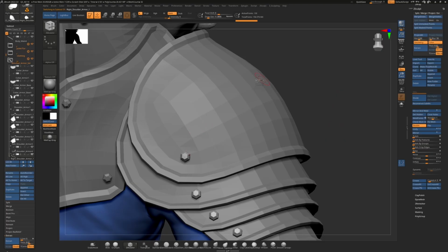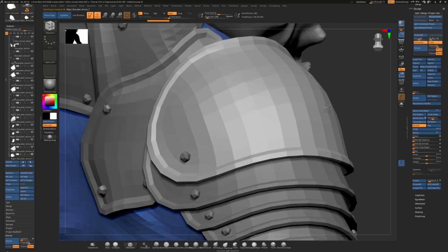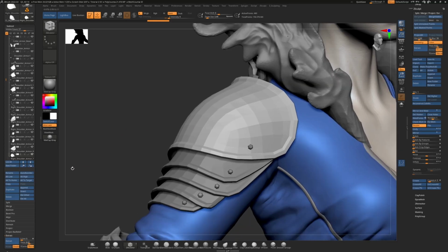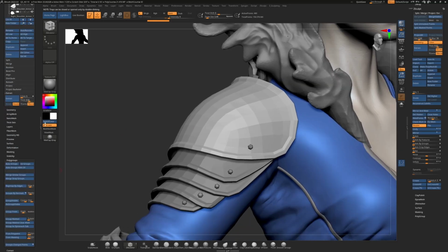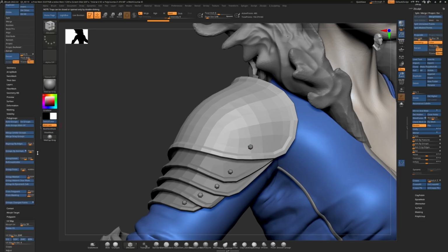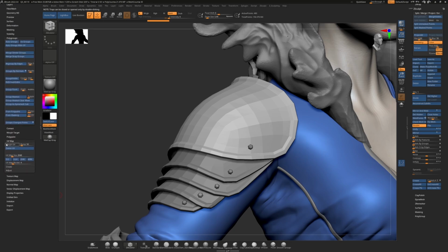The only way you can do that, again, is if you have UVs on the model that you're actually placing the IMM or curve brush on. This model specifically, this shoulder pad, I UV mapped earlier for those purposes so that I could place the bolt, but because I did that, I also now have UVs for this model.